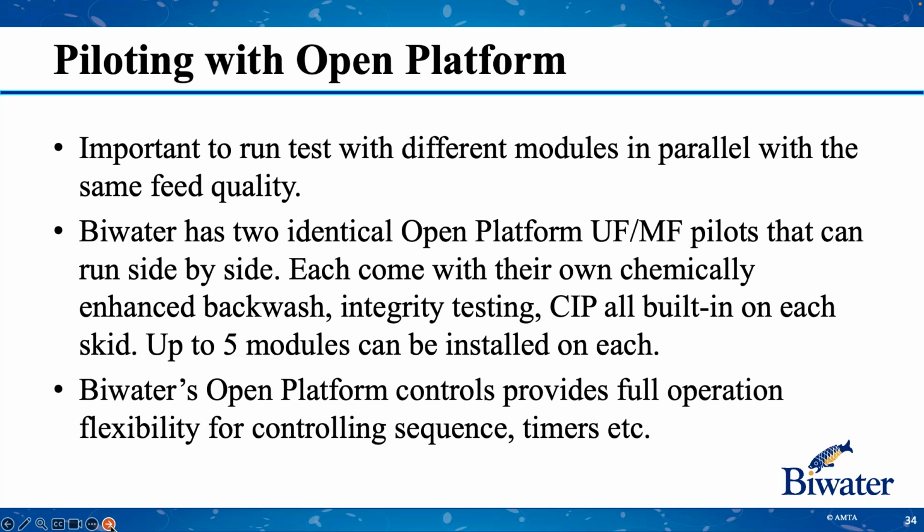Obviously, it's very important to run pilot testing for a lot of the reasons Ben alluded to earlier, and running testing with different modules. Obviously, the main key point is we want to run a system or different modules in parallel with the same feed water quality. That should be pretty obvious, so we can compare our results at the end of the day, and we're comparing apples with apples.